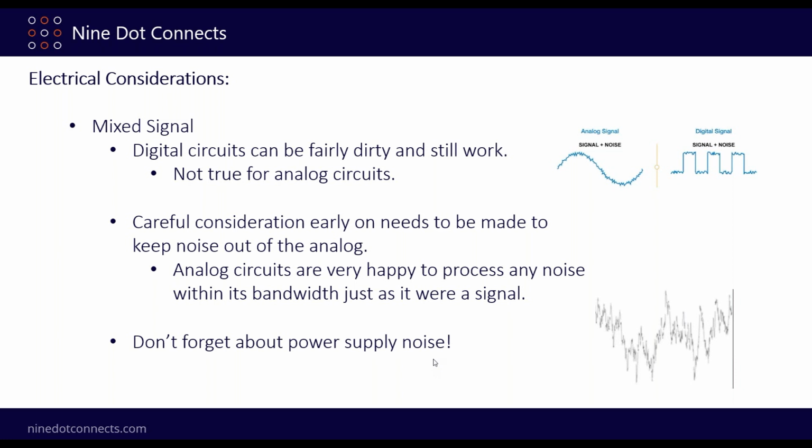That's probably the biggest thing in an analog circuit, is to make sure your power supply noise is low. Make sure you're measuring it correctly. Sometimes we measure power supply noise incorrectly if we have large ground loops and things like that. So measure the power supply noise and get to know how to measure power supply noise properly.